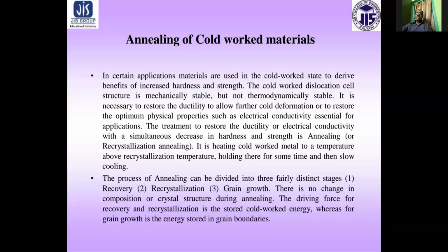So it is necessary to restore the ductility to allow further cold deformation, or to restore the optimum physical properties such as electrical conductivity essential for the application. The treatment to restore the ductility or electrical conductivity with a simultaneous decrease in hardness and strength is annealing.